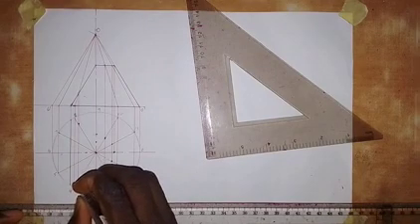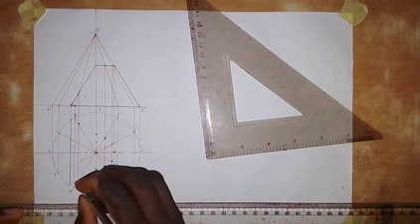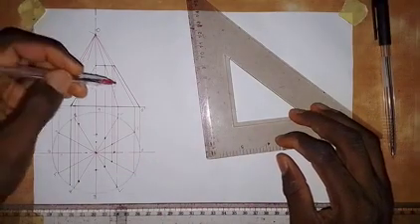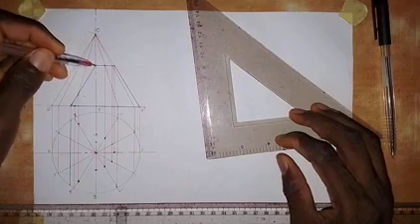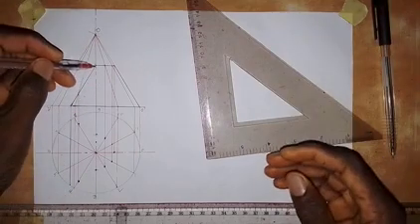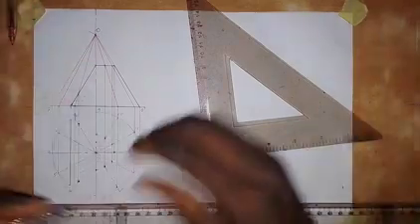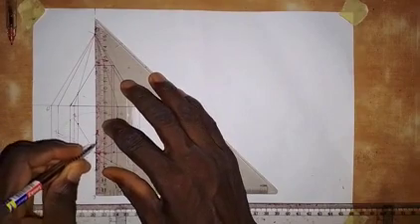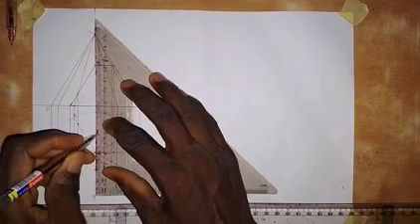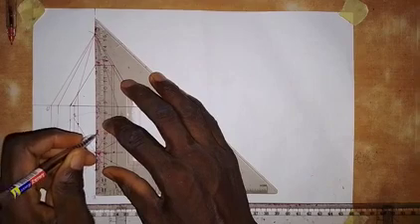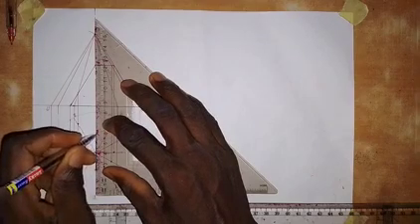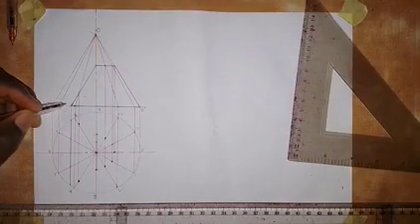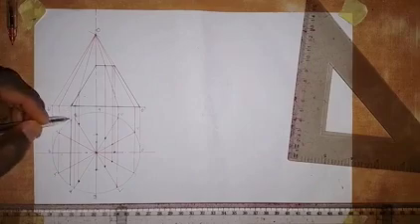Then all these points, we are going to join together with the use of a French curve. But before that, along this point, we are going to have a straight line. If you visualize what we see, we are going to have a straight line along this part. So we make this line for 3 and 9 a thick line. It is compulsory that you make it a thick line. That is how it's going to look if you have the truncated solid before you. Very, very important. I made this line a thick line because we are going to have a straight line along this part.